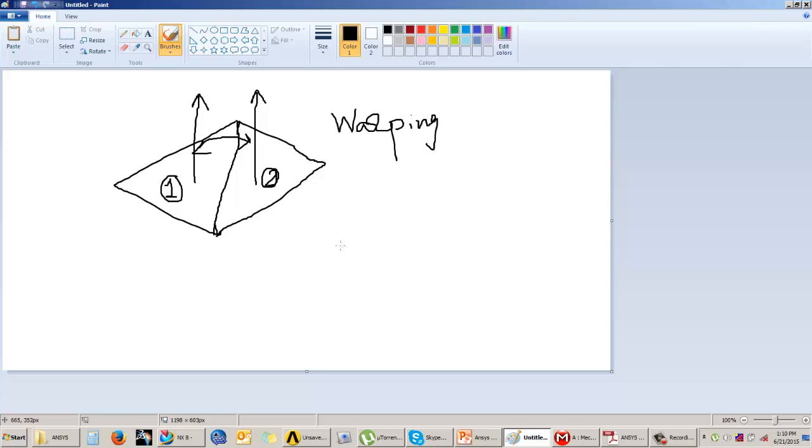Okay, so if it is a complete flat element, then the normals will have 0 degrees. That means they are not deviating, they are exactly lying in the plane. But if there are some warping angles, then the warping angle will start increasing from 0 and it will keep increasing.